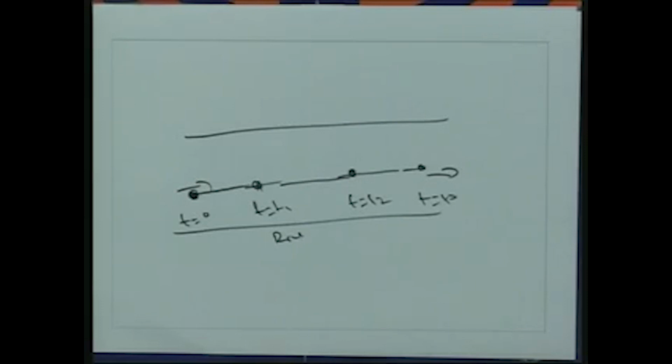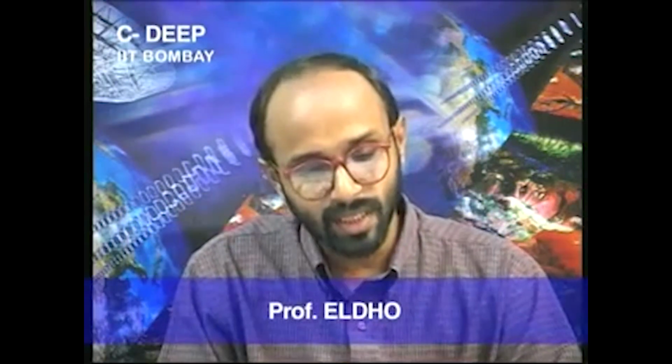In the Lagrangian method, we follow the individual fluid particles as they move and then determine how the fluid properties associated with these particles change as a function of time. So this is mainly with respect to time what happens, and the position is anyway changing with fluid particle movement, it is always changing. So the fluid particles are traced, and then what happens to those particles. That is what we are doing in the Lagrangian method. Here the fluid particles are tagged or identified, and then as time progresses, what happens to those particles. That is what we are describing.